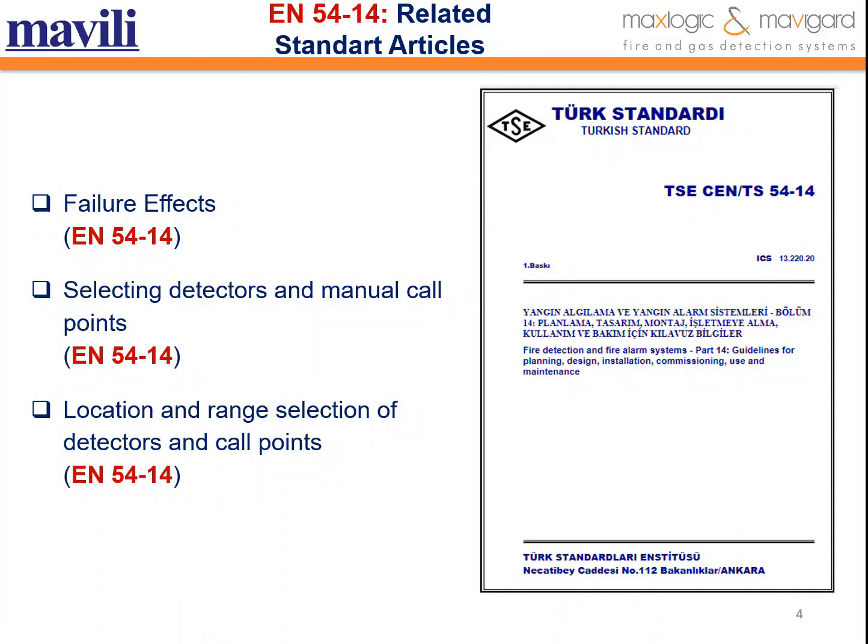In cases where people with limited mobility, inadequate or special care are required, the placement of the manual call points may require additional care. Manual call points should be clearly visible, identifiable, and easily accessible. Note that it may be suitable to make special arrangements in areas where they may be exposed to malicious use.